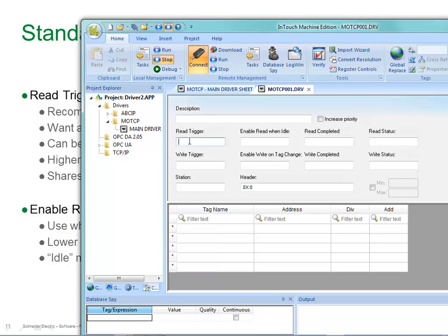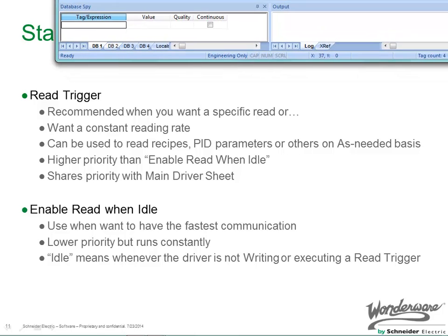And so the idea behind this word trigger, if you haven't heard me mention it in previous videos, is anytime that tag value changes. So it's not just from false to true, it's also from true to false, or it's any change. So it could go from 1 to 100, 100 to 101, 102 to 105. Just any change at all will cause that trigger to happen.